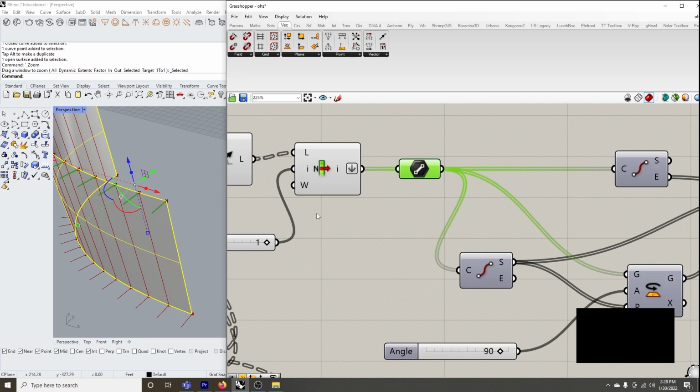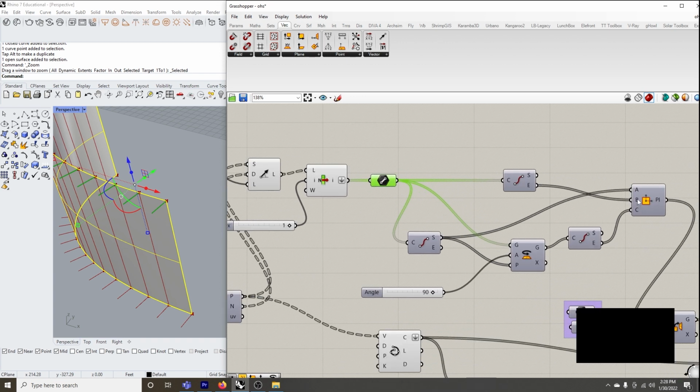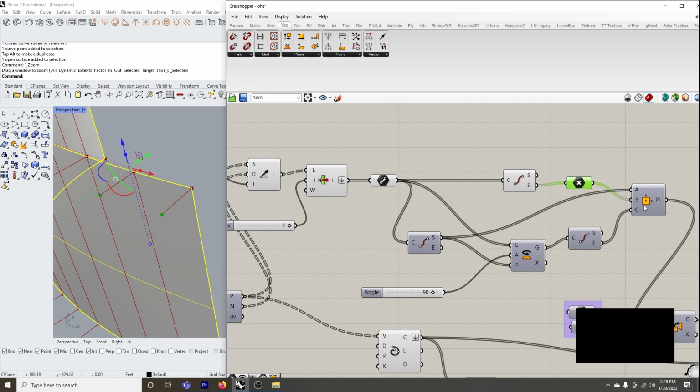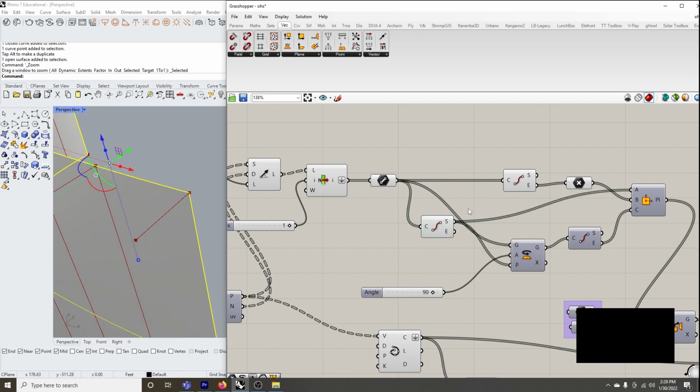Again, I'm thinking back, okay, I need to have these orientation points to work with. So the first one is the X point. It only needs 1 point. If I gave it 2 points, it would fall in an error. I just need that one endpoint. And if we type in point here, you can see that it's now selecting that 1 point. So that gave us our X direction, and then we just gave our orientation point that original one here. So again, let's just type in point so we can visualize this. That was selecting that origin point of the plane. Now this one was a little tricky.